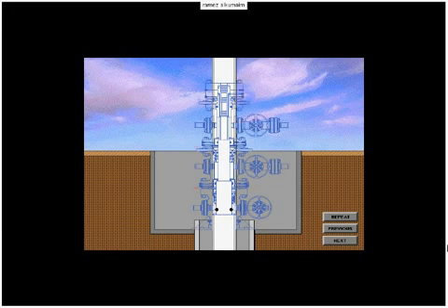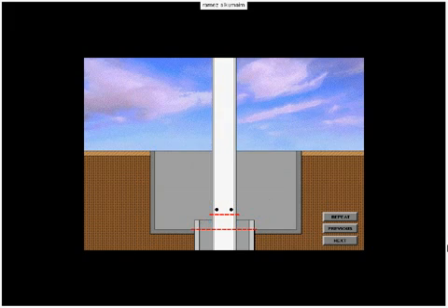The final cutoff height is determined by adding the height of each piece of wellhead equipment, plus the standoff distance between each piece of equipment and the ring gasket height. Then deduct the depth of the slip-on socket in the bottom of the casing head housing. If a base plate is used, its height must also be considered. The sum of these heights is then deducted from the cellar depth to determine the final cutoff height for both the conductor pipe and surface casing.